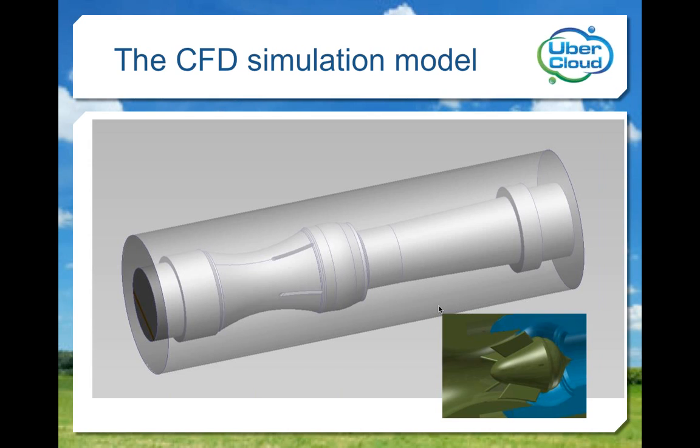Following standard practice as a new user, I set the flow rate to 500 GPM, the upstream pressure at 500 PSI, entered the data requested by prompts, left alone the default settings for meshing and solution, and clicked Solve on my local workstation.